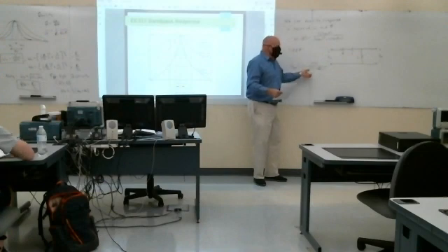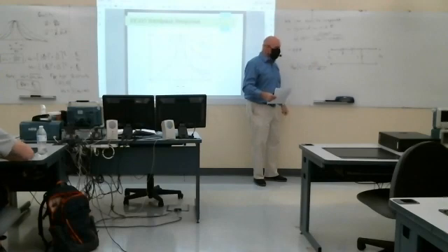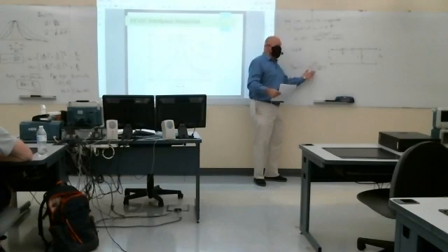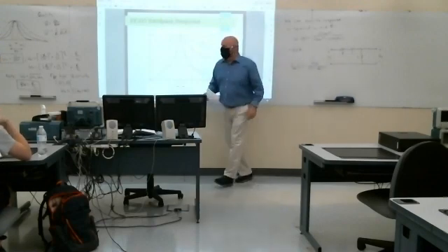You know, the other way to figure out what's going on with this is to take a look at what happens as either omega goes to 0 or S goes to 0 here. As S goes to 0, this is 0. But as S becomes infinitely large, this S squared term dominates the denominator, and you have S squared LC over S squared LC over 1 in the limit. So it's 0 at small values of S, 1 at large values.